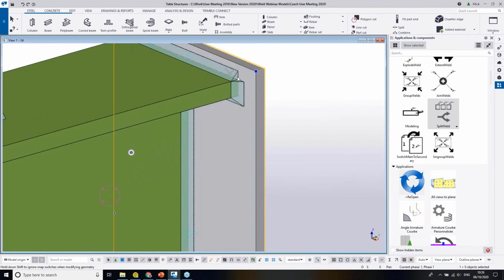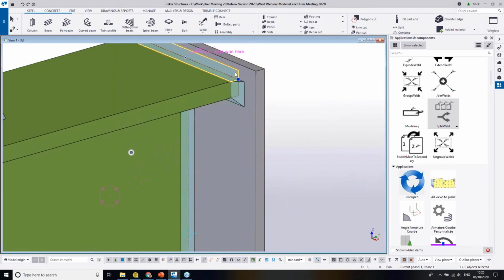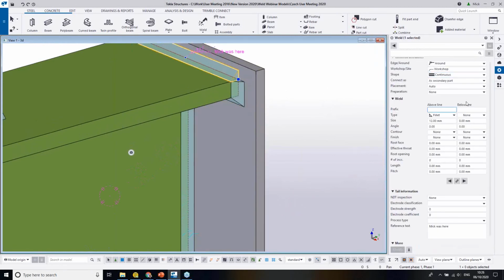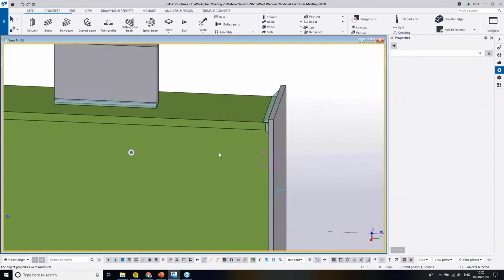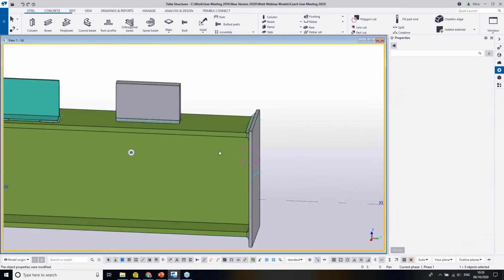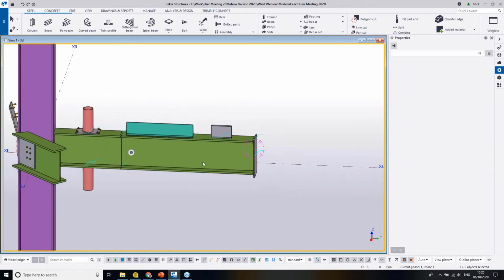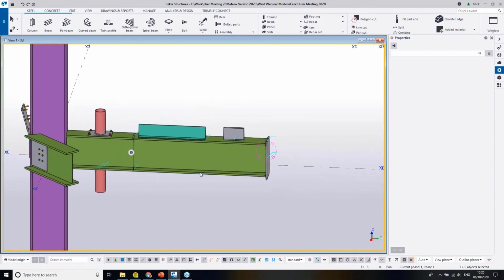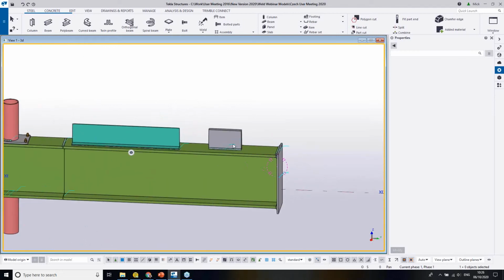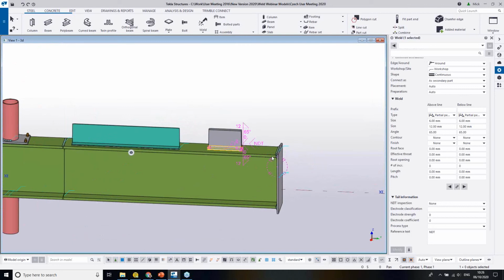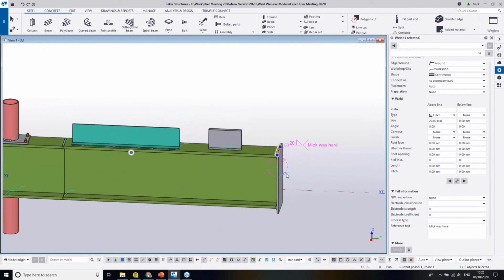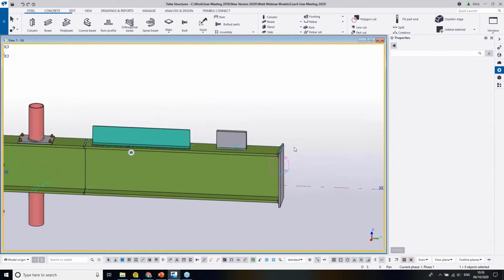And then that top weld, I can click on that very top weld itself, just individually, double click on that and say, actually, that should be, let's say, 20mm fillet at the top. So those toolbox allow you to put welds on and very quickly manipulate them into the types that you're looking for. Now, of course, the main thing is that you need to create drawings of these parts and have them correct. So again, by clicking on these, you can see the label I see on screen is exactly the label you're going to see on the drawing.